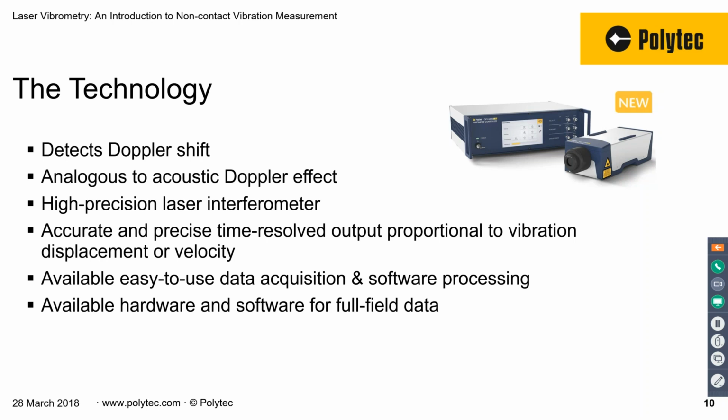For example, importing a finite element model, exporting to a finite element model for validation, or importing a finite element mesh, coarse or fine, for defining the measurement points for performing the test. This slide shows one of our most recent laser vibrometers, which I'm going to be talking about in more detail in a couple of slides from now.